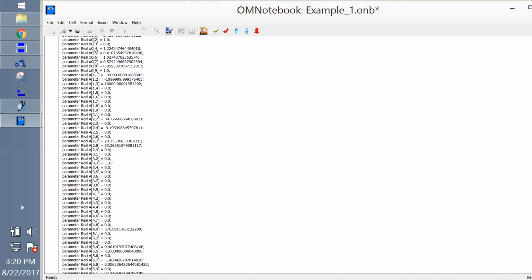I take the derivative of the swing equation, the first part, to get that. And that is 2 times pi, so that one is the multiple of pi. That's how you check that. Always check if you get a multiple of pi in one of these A matrices. Usually, if you don't get it, there might be something wrong.